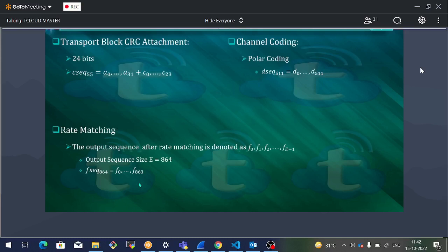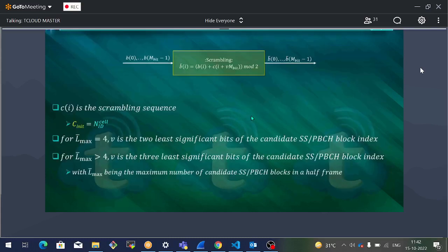Now, once this is done, you perform scrambling for the second time. There is a 2-level scrambling that works for this PBCH data, but this time you scramble all the bits. So you take c_init, the x2 initializing condition to generate the scrambling sequence, which is N_cell ID.